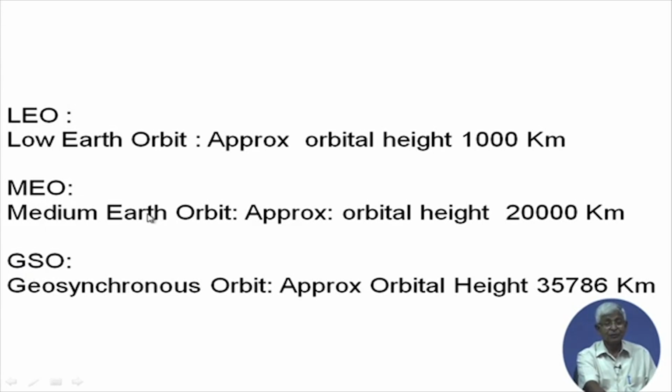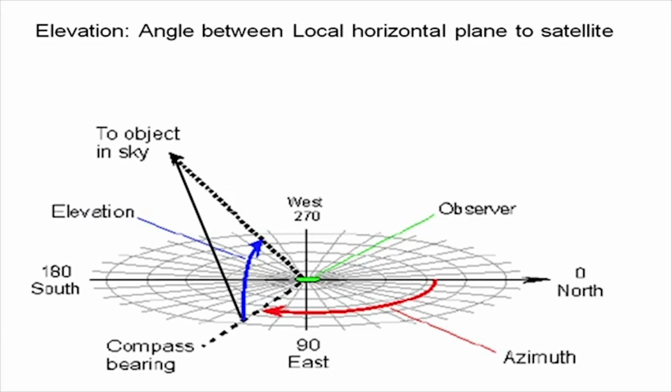Okay, now, this is what we have seen about orbits briefly, but where is the satellite? It can be defined in terms of the subsatellite point, but wherever you are on the Earth's surface, you have to point your antenna at the satellite, then only you will get the signal. So, you must know which direction the satellite is in and how to look at it. Let us do some look angle understanding and calculation. Here also certain common terminologies are used, which are called azimuth and elevation.